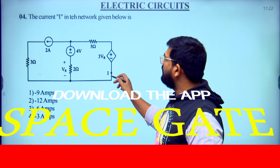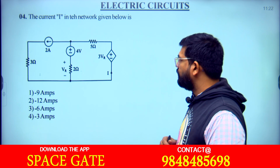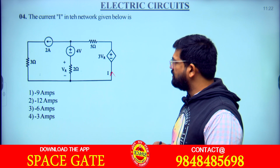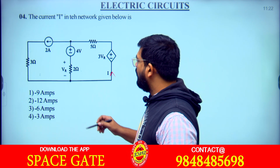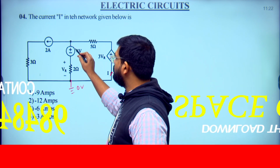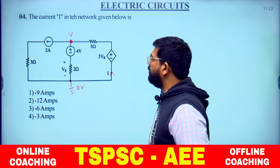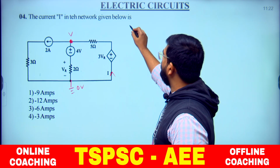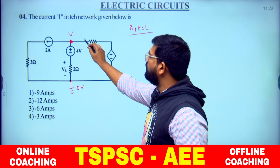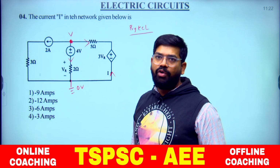The current I indicated in the network shown below is what? This current, with this direction only, is being asked. Look here, I am assuming this reference node voltage is 0 and this node voltage is V. Now by the nodal method, applying KCL at that node, I am assuming all are outgoing currents, this one also outgoing, and here the outgoing current is already given.